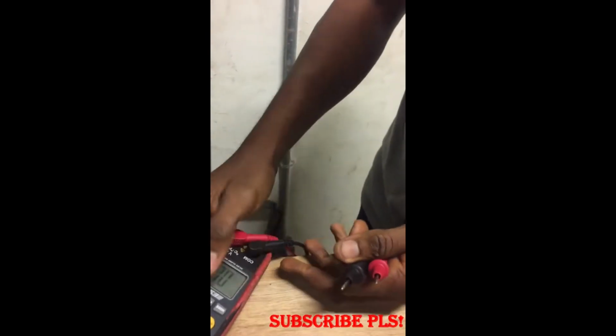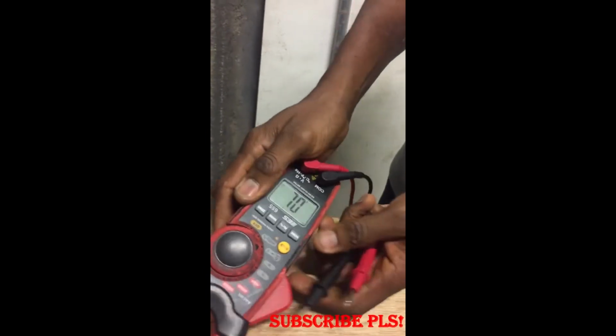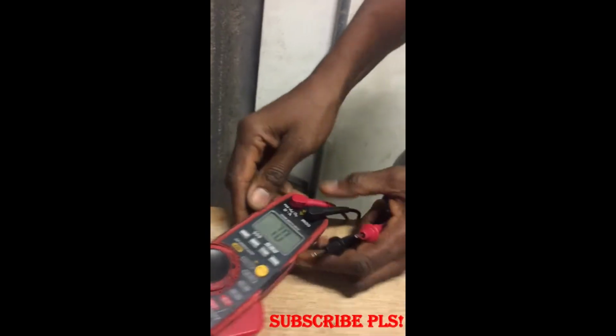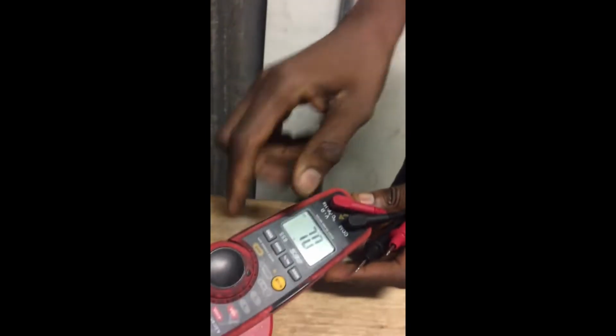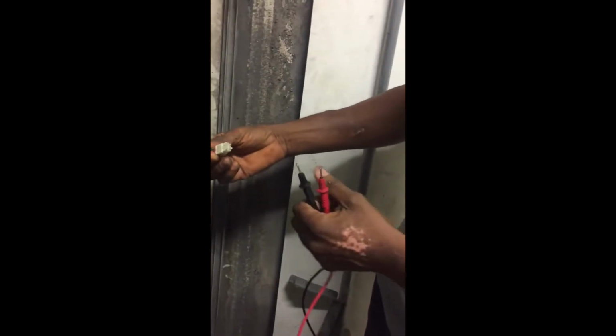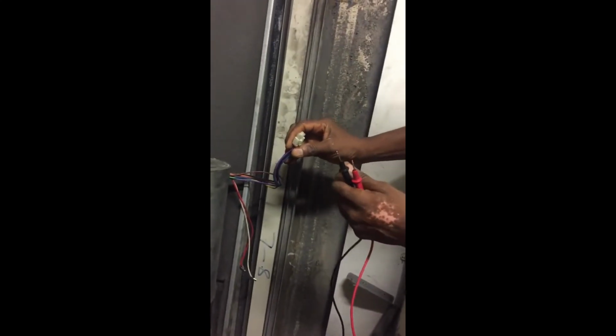You set your meter at resistance range, and point to the meter. Look closely. You can see it's on resistance range. So you get the first set of cables, which is for the speed control. Now you need to find out which of the cables is the common or the neutral.